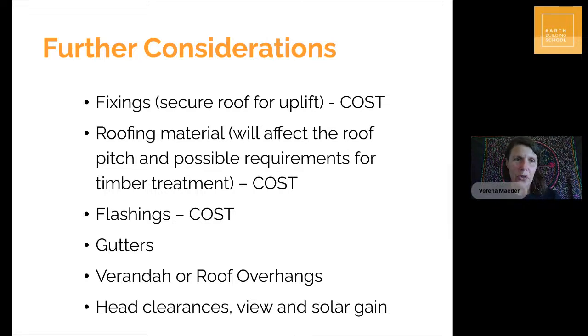And further considerations when you're designing: compare the size of timbers, price them, compare costs depending on material quantities. Really look at the table and see what kind of fixings you require, because the fixings are definitely a cost.